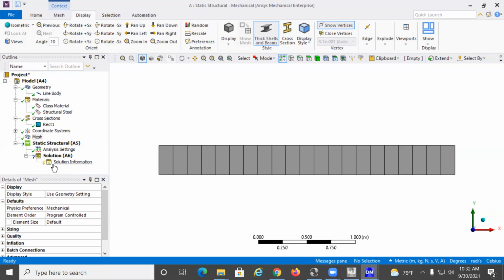I have to say that every time we create a mesh, we have to make a conscious decision about what type of elements we are going to be using for that mesh. And in some cases, we use a hybrid mesh, more than one type of element. Here we are looking at a simple problem where we're going to be using beam elements. And as I mentioned beam element, I have to tell you that the beam element in ANSYS can be used to model a beam, a shaft, or even a bar in 3D. So it's a very capable element, unlike the simple spring element that we used when we did the hand calculation.